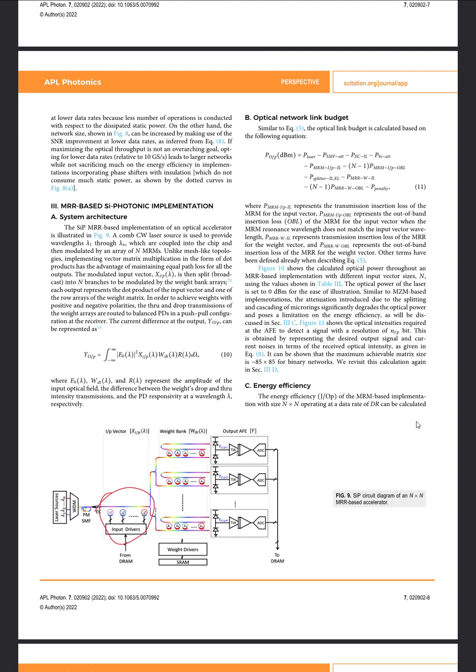This leads to a sizable reduction in driving power. Microring modulators are much more sensitive to fabrication mismatch and thermal drift, however, and the scaling of power consumed by the heaters degrades the overall efficiency of this network.